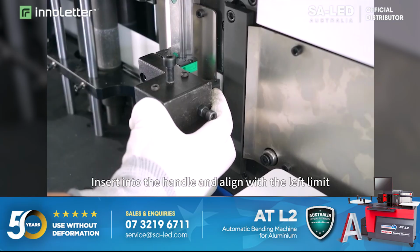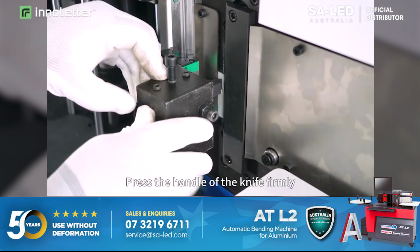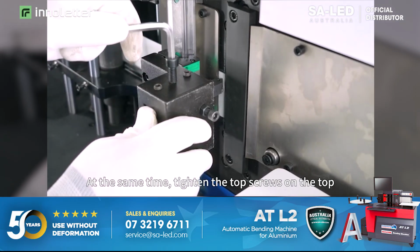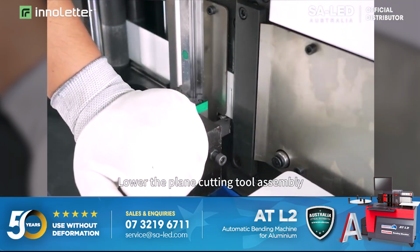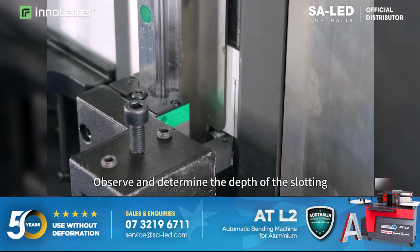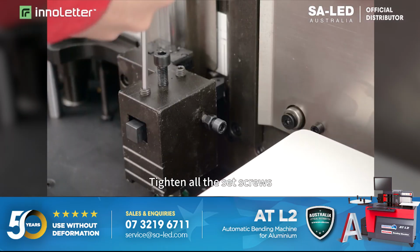Insert into the handle and align with the left limit. Press the handle of the knife firmly to ensure it is tightly against the surface of the material. At the same time, tighten the top screws on the top. Lower the plane cutting tool assembly to make it cut the surface of the material. Observe and determine the depth of the slotting. The depth can be adjusted repeatedly until it meets the standard. Tighten all the set screws.